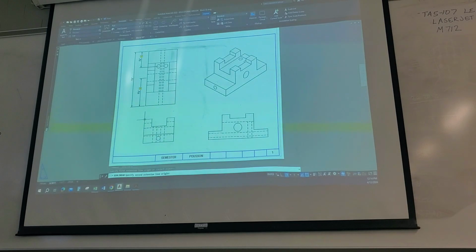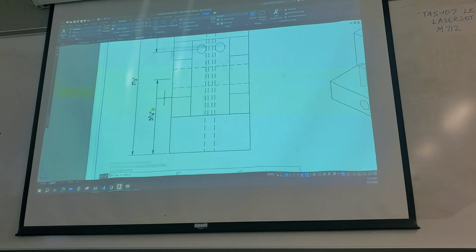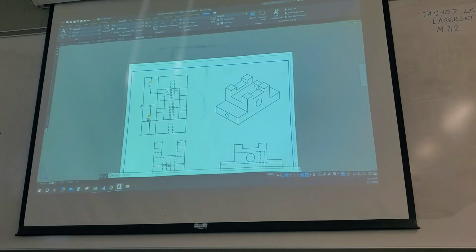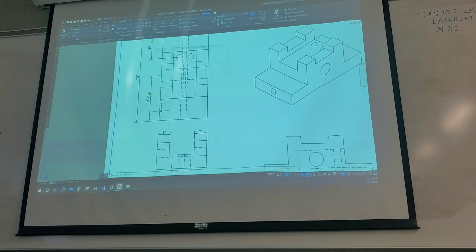So I can go through and dimension this object and make some good, clean dimensions. Now here's something you'll see when you're dimensioning in 3D. See those little yellow boxes with that exclamation point in there? The reason that is on there is because when we're dimensioning this 3D object, even though I move my cursor down there and pick a point that recognizes that end point, if it is not an object snap point of that object itself, AutoCAD will give you an error.